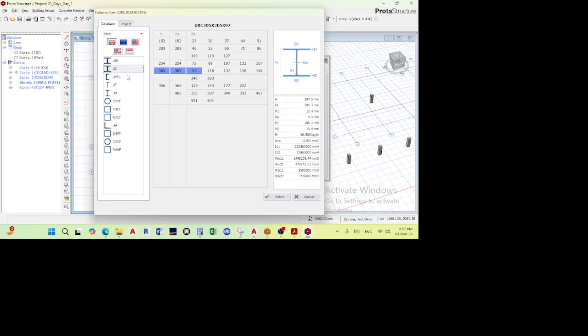But also bear in mind, when you're selecting a steel column, bear in mind where you're placing it. You're placing it on a concrete column. What is the dimension of the concrete column? We're using 400 by 400. So now imagine I've got a 400 by 400 concrete column, and then I'm placing another maybe 406 here. That's too big, because it needs to sit on a plate, and then also the anchor bolt. So maybe if I desire a bigger column, I need to design bigger stub columns, right?